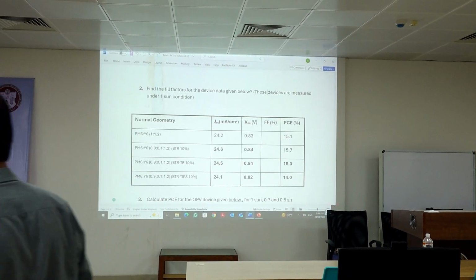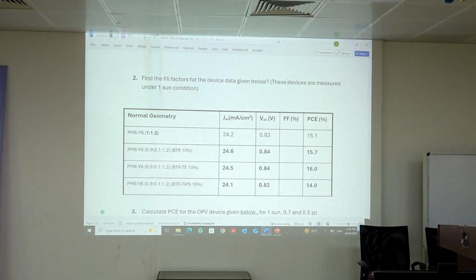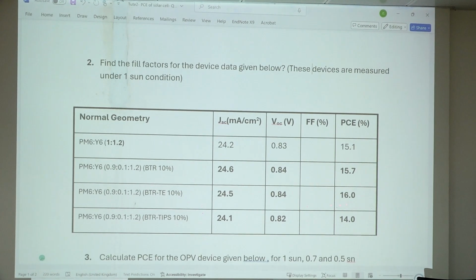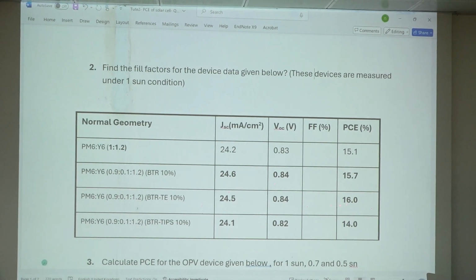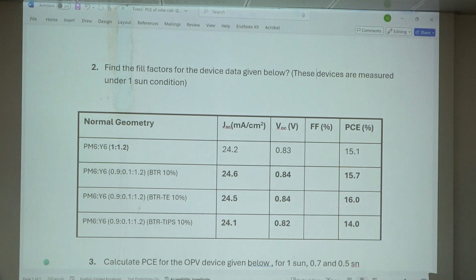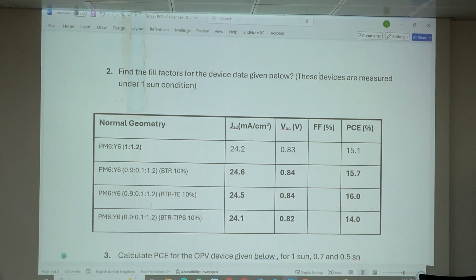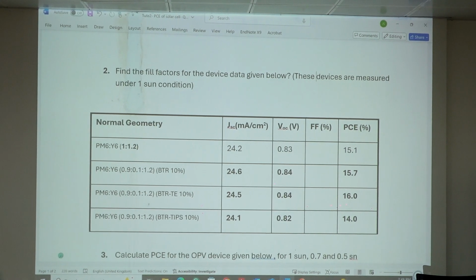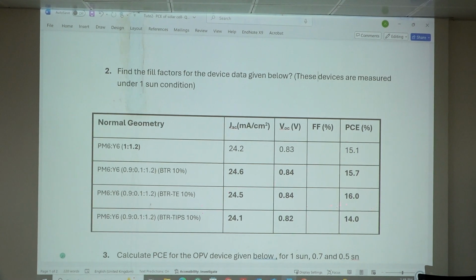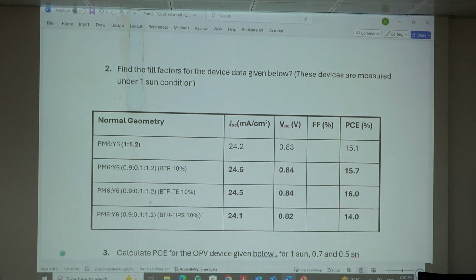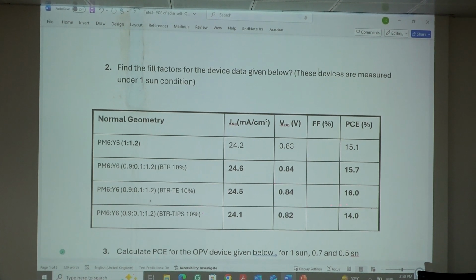How much are 70? Yeah. 1 kilowatt per meter square. No, 1000 watts per meter square, 1 sun. 1000 watts means 1 kilowatt per meter square. That's 1 sun. We calculate it as P at 1 sun. You just put 1, because when you put 1000 watts, we are asking milliwatt. That's why we cancel. Everything will be cancelled out. That's why you don't worry about those things.